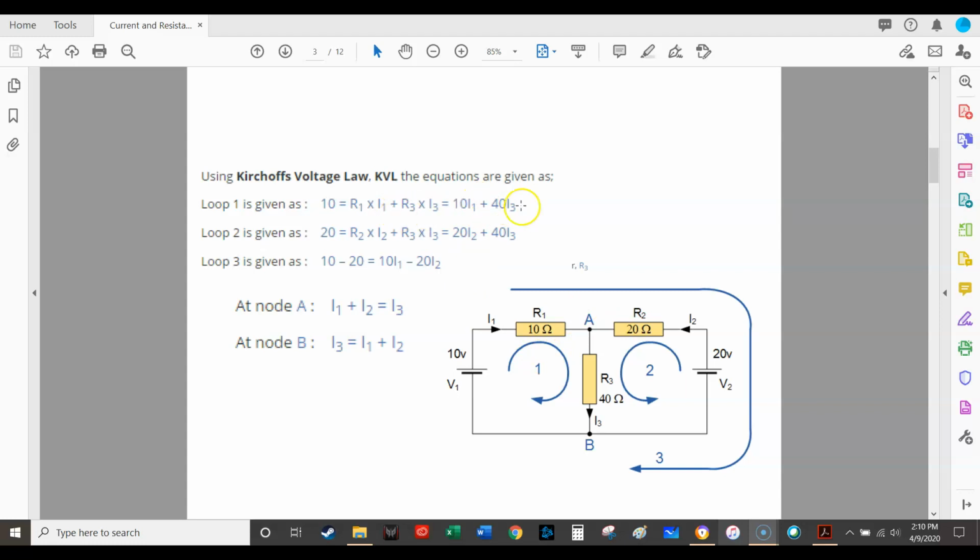So we're going to be trying to identify the currents. So we don't know what I1, I2, and I3 is, but by combining these equations together, and also these other two equations, well, actually this equation, just one of the nodes will work. So you have 1, 2, 3, 4 equations to solve for 3 unknowns. Completely possible to do. Okay?